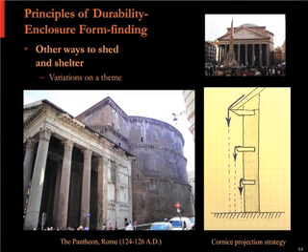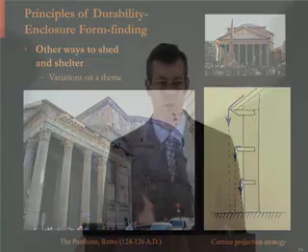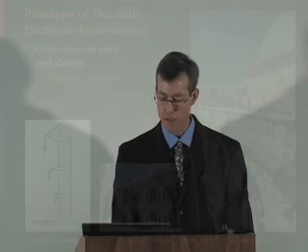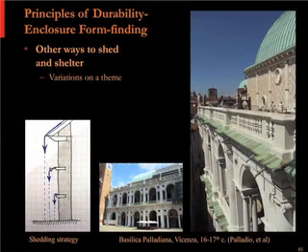And then this same general idea is also done in masonry, but in different ways. So when they don't go to the trouble of corbelling the entire wall out, sometimes the wall is planar, but then what moves out are those cornices. And that's actually the case with the Pantheon. So that might be hard to tell in that photo at the lower left, and it's kind of hard to pick a place on this building where the cornice is intact in 3 consecutive vertical locations because it's so dinged up and chipped in a lot of areas. But it's very clear in all the reconstruction drawings that each cornice projects out beyond the one below. So they kind of made it work just by doing it with the cornices and keeping the wall planar.